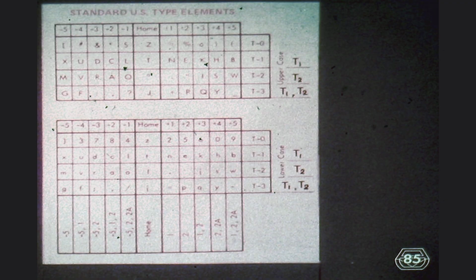Within each block or rectangle, the selection between the horizontal lines is accomplished through the tilt mechanism. The tilt latches, which must be pulled down by the positive latch bail, are indicated at the right end of each line. The rotate latches to be pulled down are indicated at the bottom of the chart. The latches that are not mentioned must be filtered out by the input section, or keyboard.